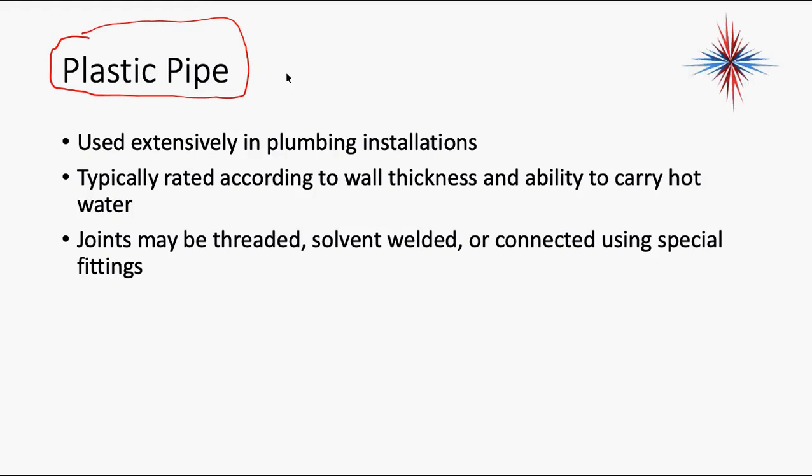I'm not used to working with this stuff. And it was a changeover period to get used to it. So, again, the solvent weld is easy. It just has to be clean. The minute you get anything on plastic pipe dirty, in other words, get sand or dirt on the ends or any contaminants on the end of it, it doesn't seal properly and it will leak.